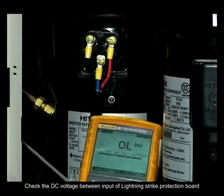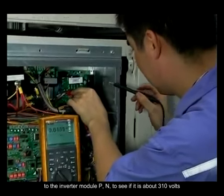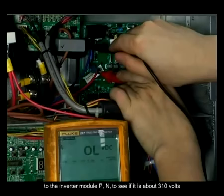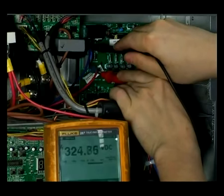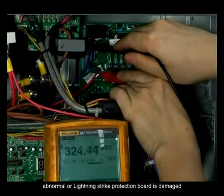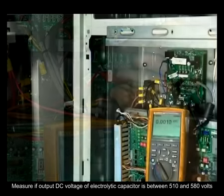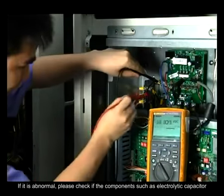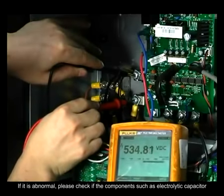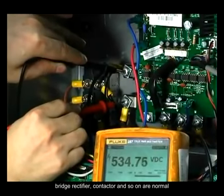Check the DC voltage between the input of the lightning strike protection board to the inverter module PN to see if it is about 310 volts, which is equal to 1.41 times the local input voltage. If it is abnormal, the voltage of the power supply is abnormal or the lightning strike protection board is damaged. Measure if the output DC voltage of the electrolytic capacitor is between 510 and 580 volts. If it is abnormal, please check if the components such as the electrolytic capacitor, bridge rectifier, contactor, and so on are normal.